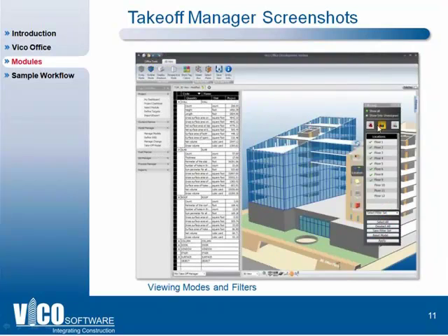The filtering panel that you can see here in the 3D view helps you to really specify a focused view on the model. So if you really want to drill down into the structural aspects of the project, you can use the filtering panel to filter out layers, element types, and specific models that you want to look at.